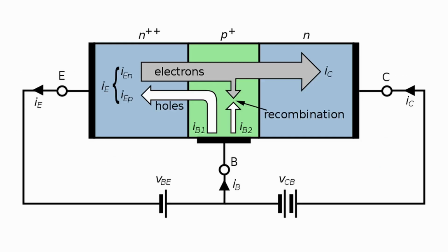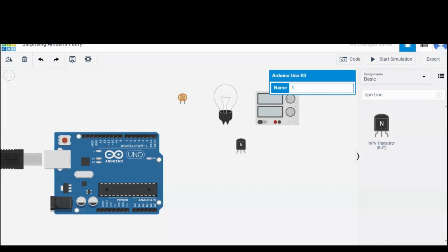The transistor in which one p-type material is placed between two n-type materials is known as an NPN transistor. The NPN transistor amplifies the weak signal entering the base and produces a strong amplified signal at the collector end. These transistors are mainly used in switching applications, also in amplifying circuit applications. So mostly at places where there is a need to sink a current.